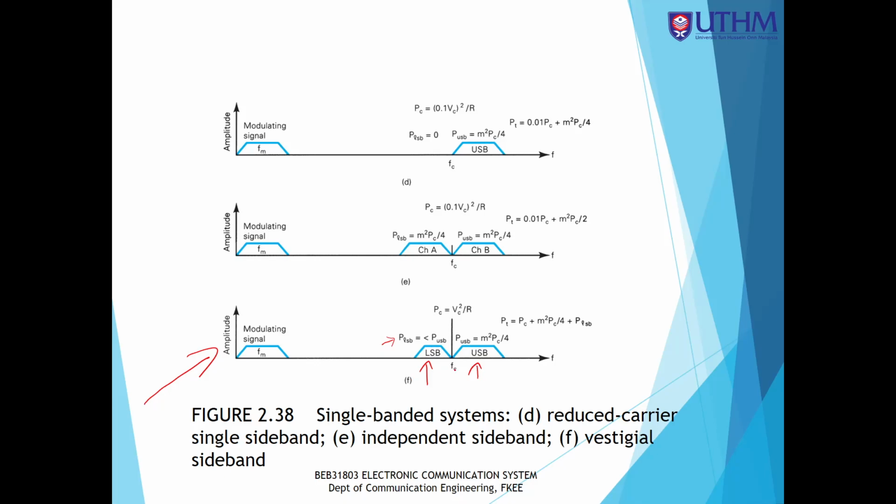In terms of the size of the bandwidth, the width of the upper band is larger than the width of the lower band. That's why the upper sideband here is more suitable for the video, and the lower sideband is more suitable for the audio signals. And we also still have the carrier component. If you see from the picture above, picture E, this is for the independent sideband.